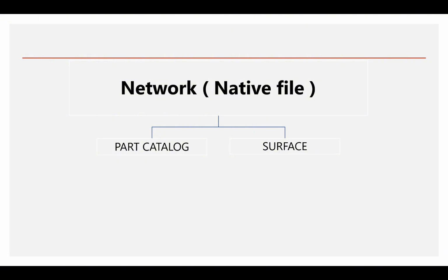And as we said, the surface needs to be checked and verified that it's covering all the right of way. If it's not covering all the right of way, I will have some structures with zero level, because this surface will be my reference for cover level for structures and cover level for pipes also in the profiles. So I need these two major things in order to create a correct and healthy native file.